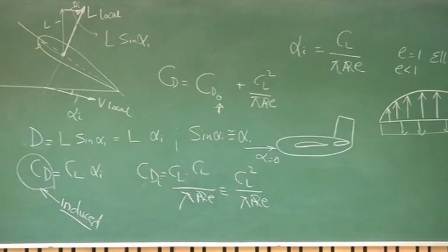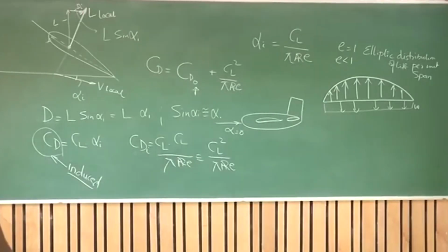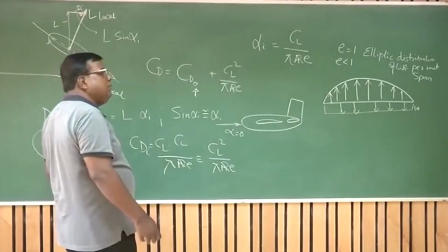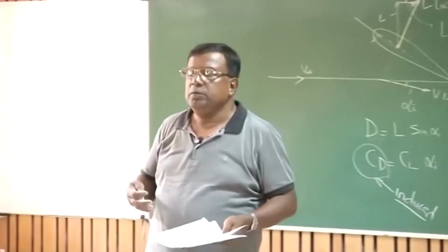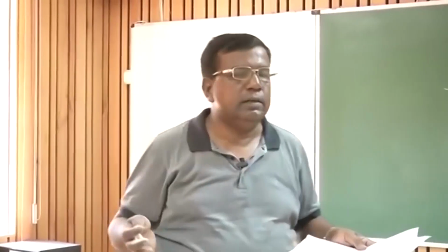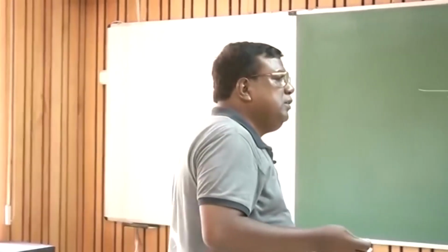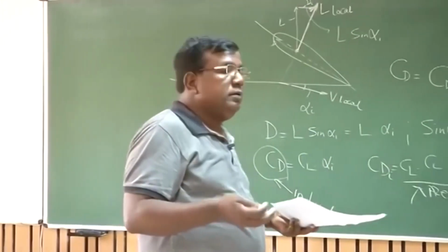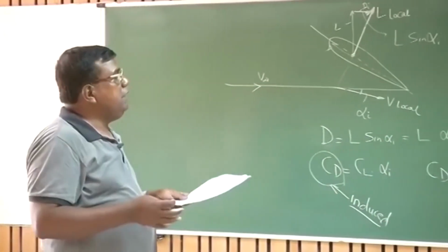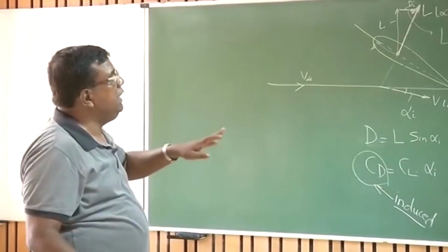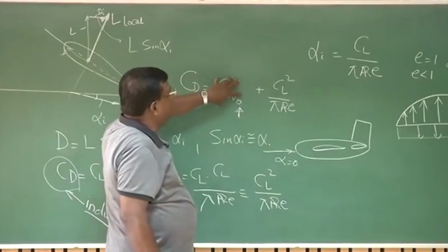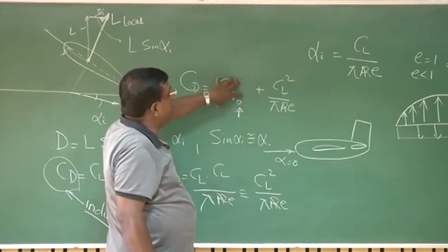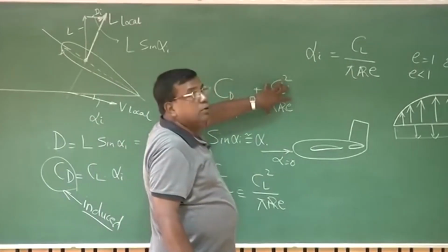For a cambered aerofoil, we write CD at CL equal to 0, and as we progress, we see that sometimes we represent this drag coefficient using CD minimum also. Those are a matter of detail. For the present, only understand that the drag coefficient will have two components, one because of parasite or zero lift drag, and the lift induced drag.